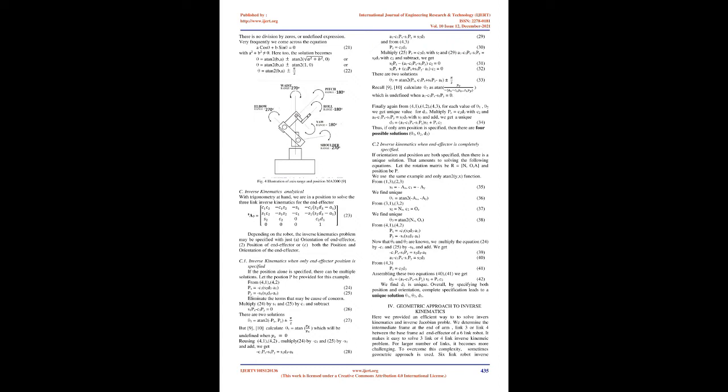The sin⁻¹(value), cos⁻¹(value), and tan⁻¹(value) are insufficient to cover all quadrants for accuracy. Some authors use the inverse functions erroneously. For example, we explore solving the following equations for θ1, θ2, d3 from the position of the robot arm. Their method would solve them as follows. Their approach runs into undefined values for θ1, θ2 on using standard inverse trigonometric functions. There are several issues with this calculation. First, cancelling the negative sign creates a discrepancy of 180 degrees in the angle.